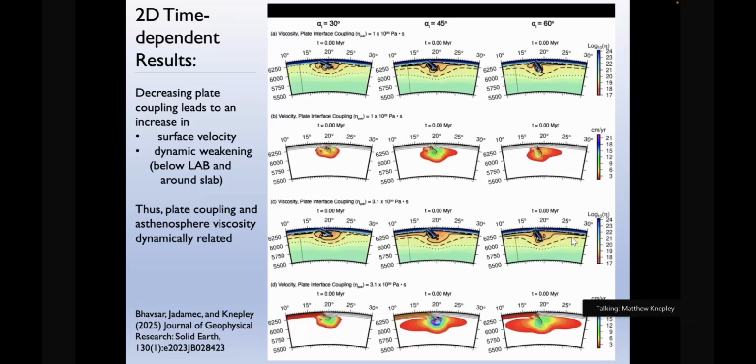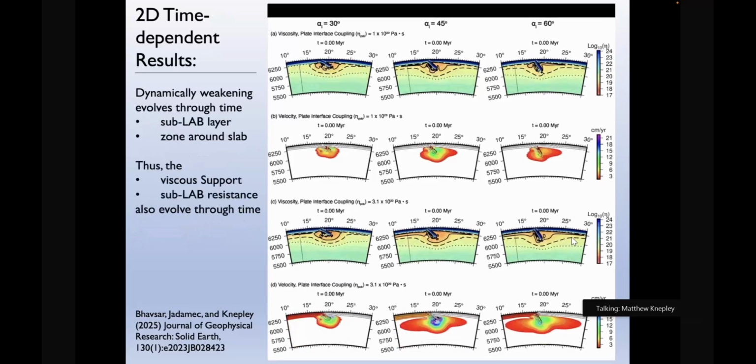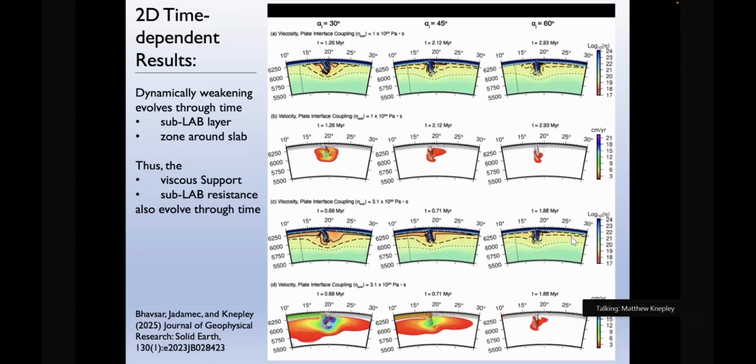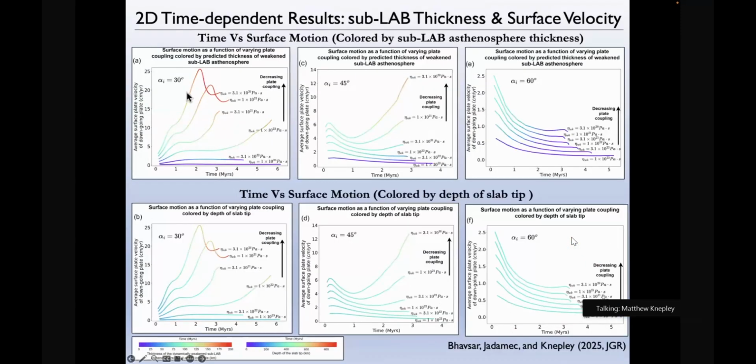And we could not solve these problems without the composite viscosity. You get these large viscosity variations, large velocity gradients, it's hard for the solvers. So in this code, we have the full multigrid. Other versions of CitcomS have used PETSc to facilitate that process.